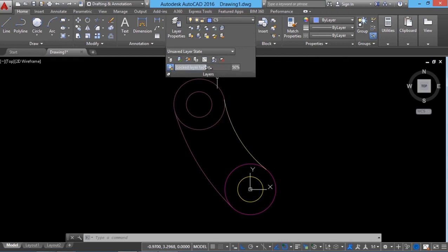And this is used to control the fading of the locked layer. You know that when you lock a layer, the objects in that layer will be shown faded, and that fading percentage you can control here. Now I'll reduce the fading percentage. Then if you lock a particular layer, now you can hardly make out the fact that it is locked. But when you increase the fading percentage, you can easily make out the layer which is locked. So that's the use of this particular slider. So that's all about the various shortcuts in the layer panel.